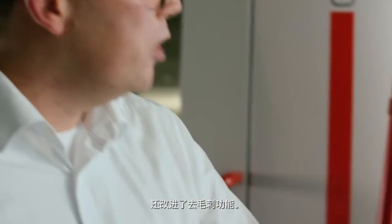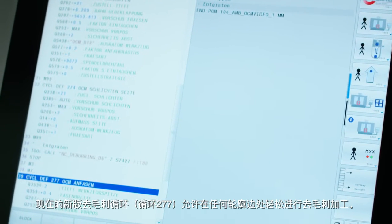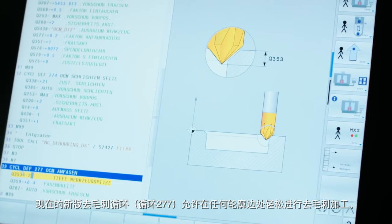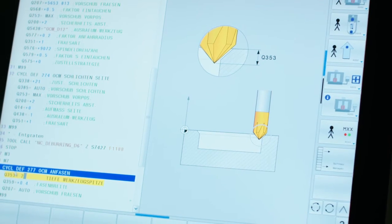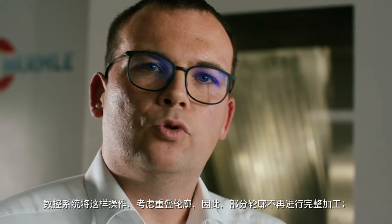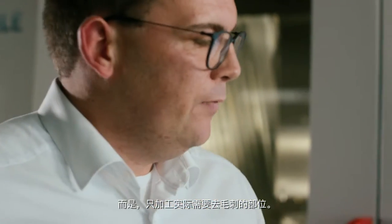The next enhancement that we'll look at is the topic of deburring. The new deburring cycle, Cycle 277, now offers us the possibility of simply deburring contour edges. What the control does, it takes overlapping contours into account here, so that not all contours are completely machined again. Instead, only those areas that can actually be deburred are machined.